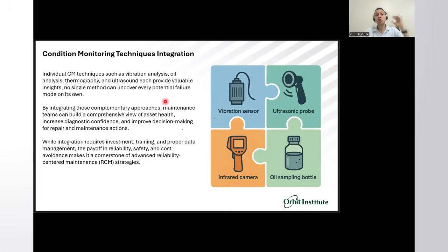So again, each one of them, vibration analysis, thermography, ultrasound testing, and of course oil analysis, provides valuable insight. No single method can uncover every potential failure mode on its own. Each and every condition monitoring technique has its own strengths and its own drawbacks as well.